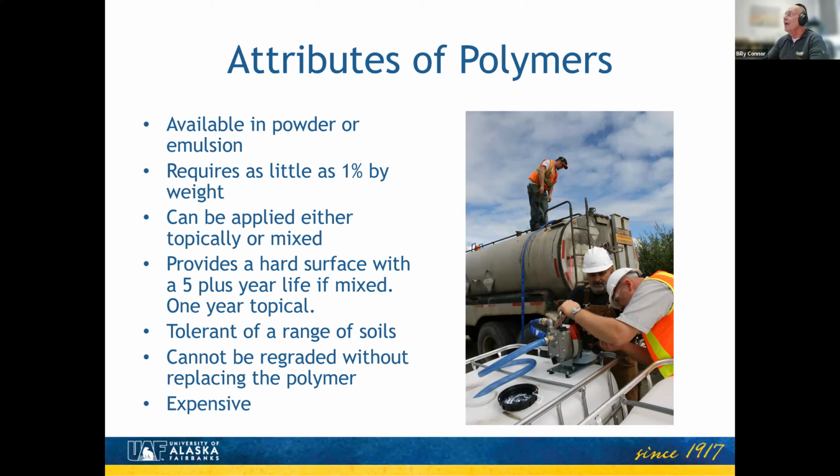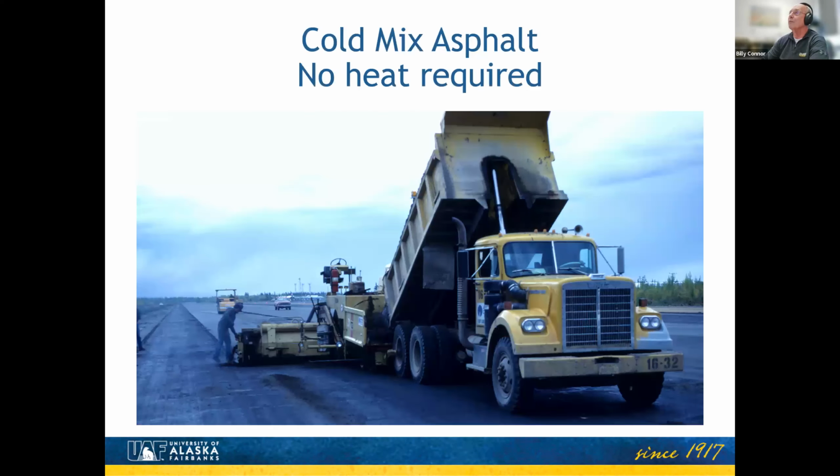It works pretty well. It does not work very well if you're using it on clays or organic clays. I would not use it there. We tried it. It didn't work at all. So that's not a good choice for these materials. As I say, you can't regrade it without replacing the polymer. And it is a little bit expensive, but if you do a life cycle cost on it, for your applications, it could be cost effective. But it does require you come up with some upfront money to be able to put that down.